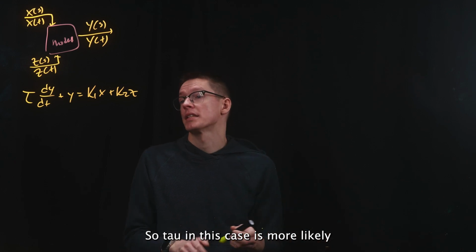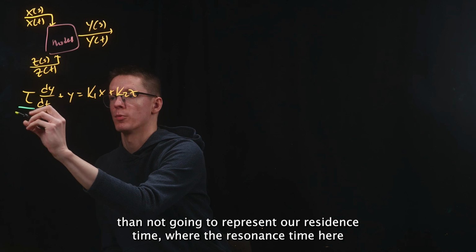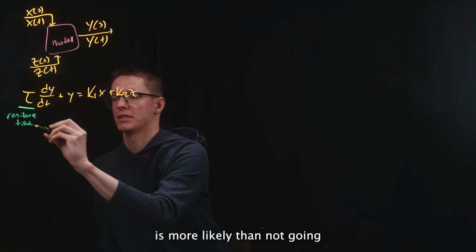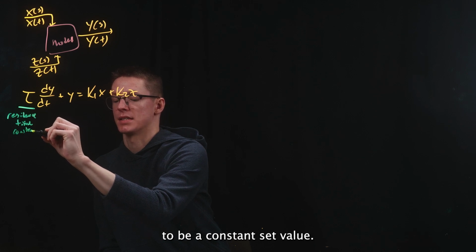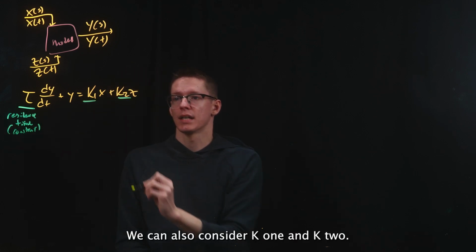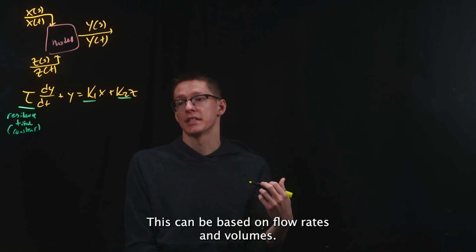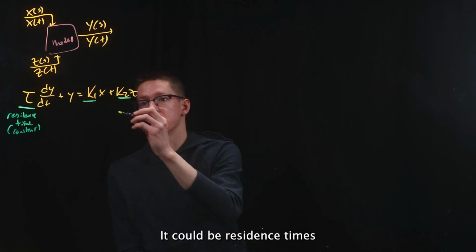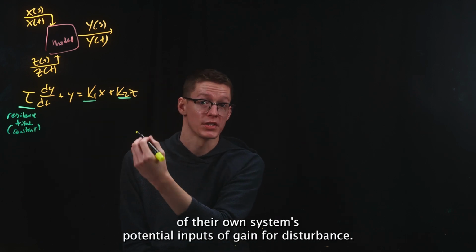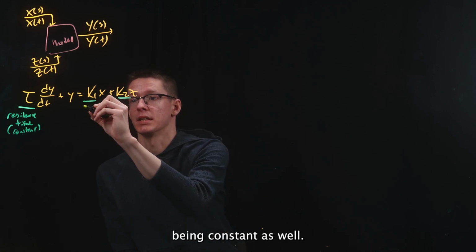Tau in this case is more likely than not going to represent our residence time, where the residence time here is more likely than not going to be a constant set value. We can also consider K1 and K2. Now, this can be based on resistances, flow rates and volumes, or residence times of their own systems, potential inputs of gain for disturbance, but these are more commonly gains, and these are going to end up being constant as well.